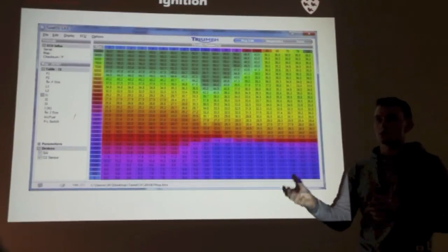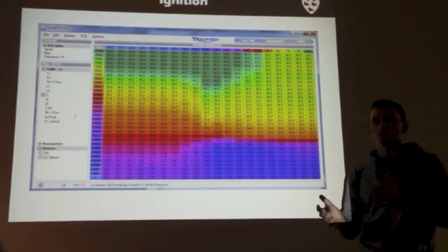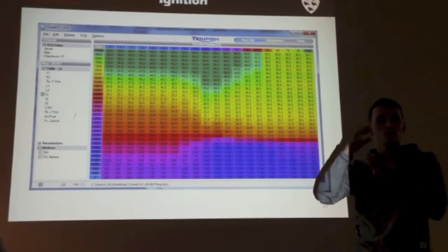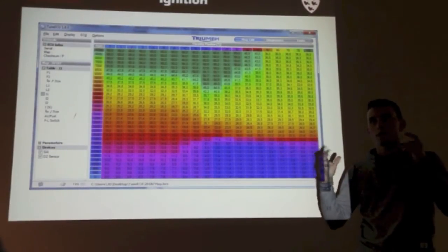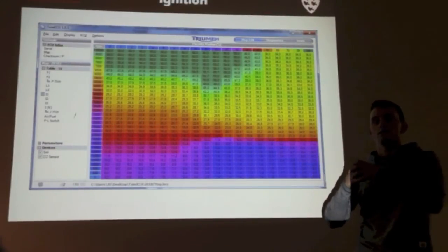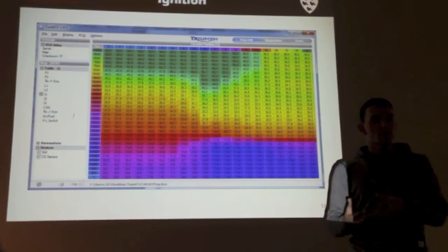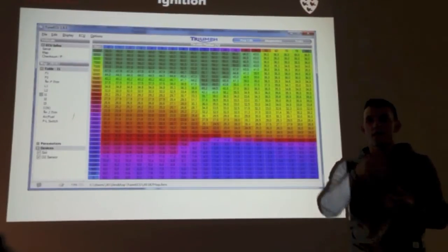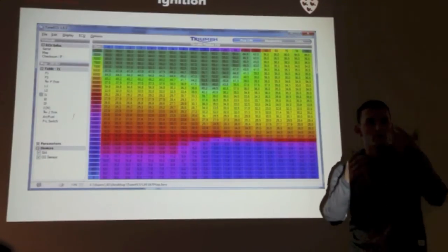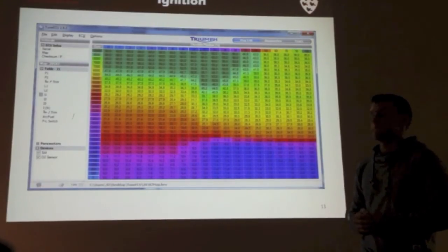Because if you start your ignition too early, then even if the burn rate of your air fuel mixture is quite fast, your piston will still be going upwards in its stroke, and thus you're counteracting the work done by the energy released by the air fuel mixture burning. By that happening too early, you put a negative force on the piston, trying to slow it down before it gets back around to top dead center.